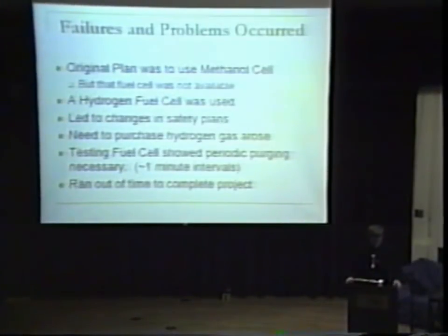And for testing the fuel cell, when Dr. North and I decided to test it, we noticed that the voltage and current were both extremely low at first. Looking at the owner's manual, it said you had to purge it every minute. The fuel cell had two ports, one side inlet and one side outlet.